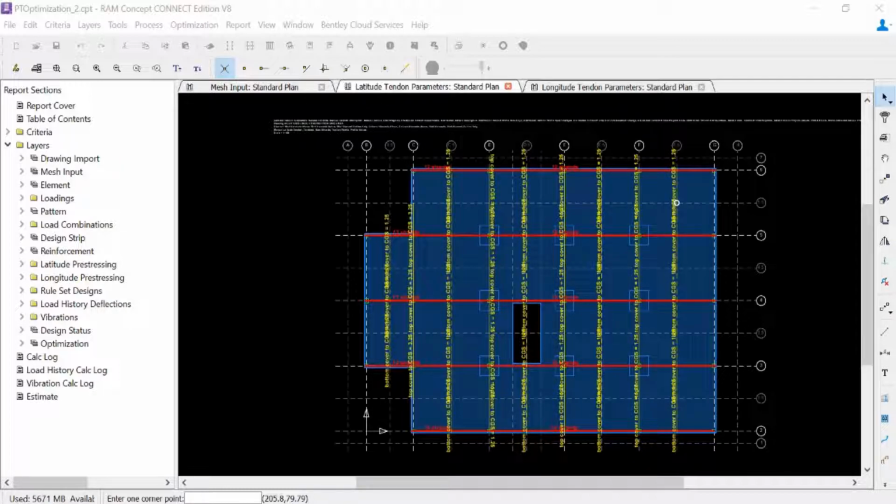Now, groups will allow for the selection of optimizable post-tensioning objects to control some of the object's properties. Whenever a group is assigned to either tendons in the model or a profile point, it'll force the optimizer to evaluate those different types of objects together to come up with a common solution. Please be aware that if you are using grouping, you may not always achieve your most optimum result, since now you are grouping certain objects together.